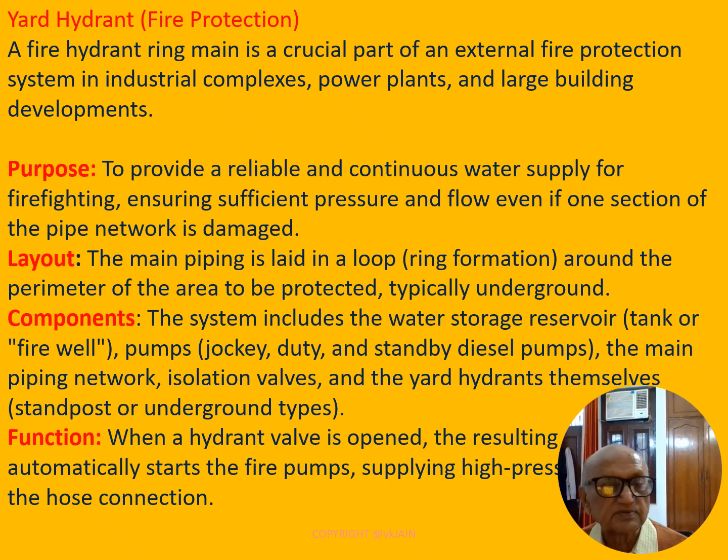The main piping is laid in a loop formation around the perimeter of the area to be protected, typically underground. By underground I mean the ring pipe has to be provided underground.